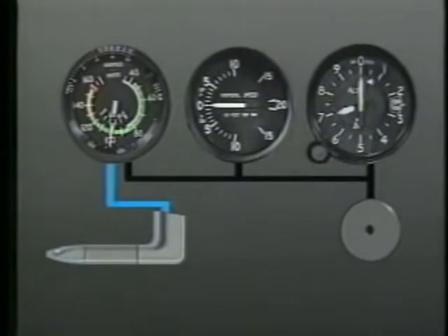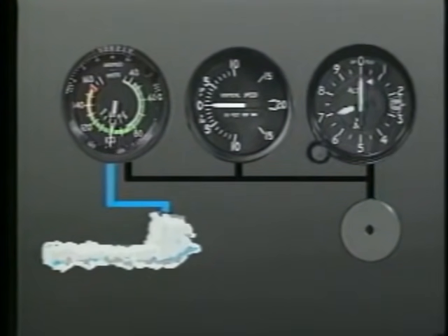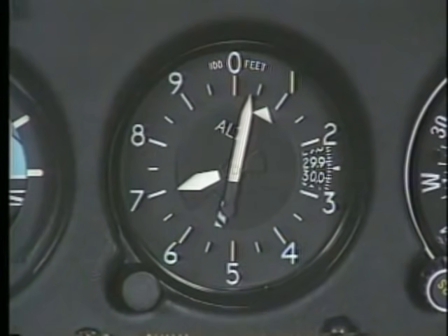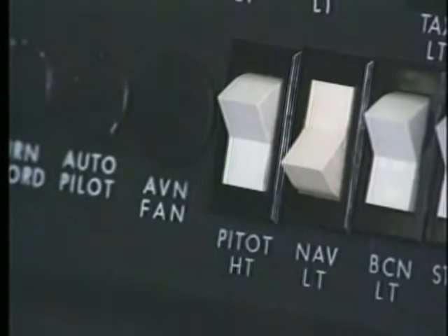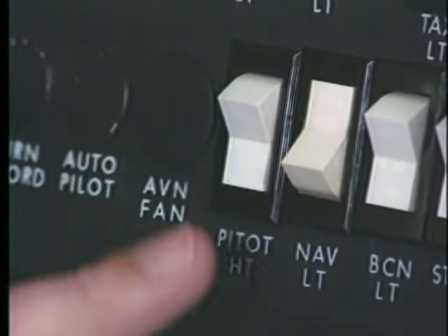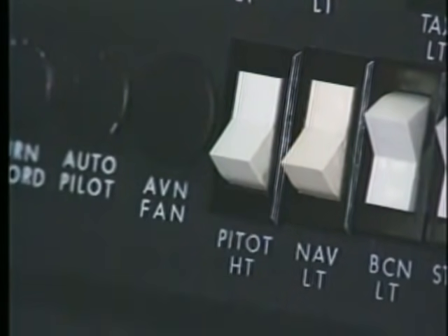However, if both openings are clogged while the static port remains open, air pressure remains in the line and the airspeed indicator now performs like the altimeter. As the airplane climbs from the altitude where the blockage occurred, the airspeed increases. Conversely, as you descend, the airspeed decreases. To help prevent blockages in the pitot system when operating in possible icing conditions, you should make sure the pitot heat is on if your airplane is so equipped.